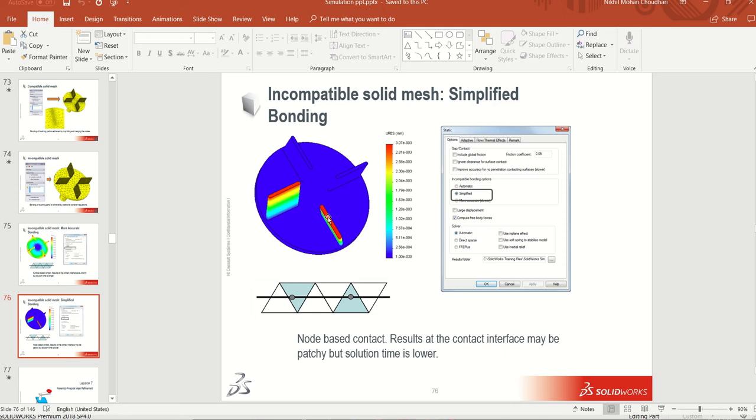So at the bottom face of the blade there are nodes. So we consider those nodes only, and this planar circular face is called the target face. On that we will consider the elements: whatever nodes are at the bottom of this blade, they share some elements. So if this node has this element, then for calculation we are going to consider this element and this element. In between these two nodes we don't have any node, so it won't consider these bottom elements of the target face, so it will create patches.